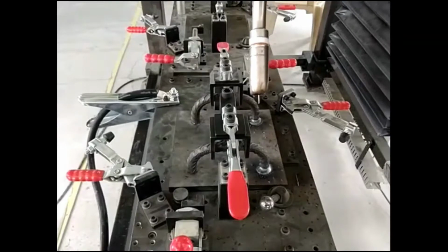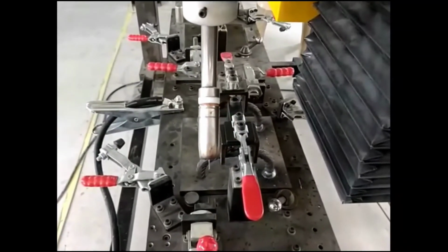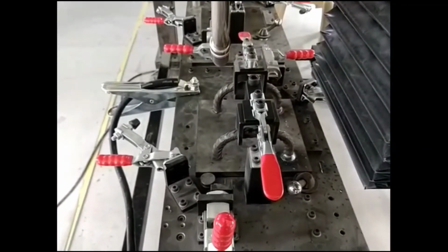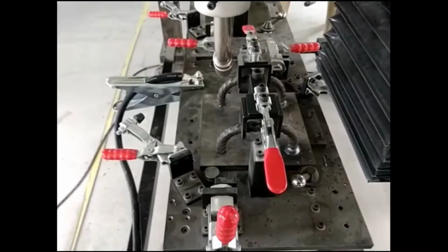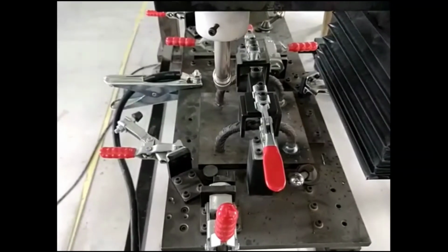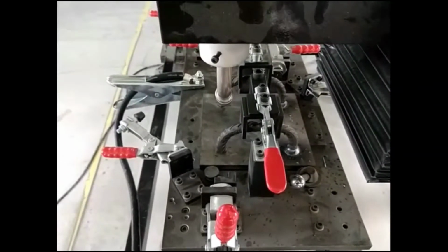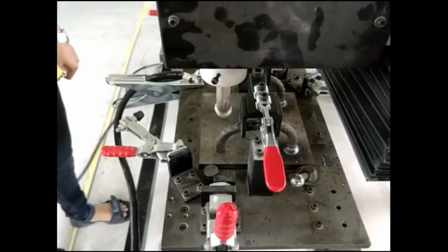Now if you see, the axis interpolates, comes to that particular position and starts welding the TMT bars. The biggest challenge that we faced here is that during the weld, if we do not interpolate the axis, we don't get the exact circular profile of the part that has to be welded.